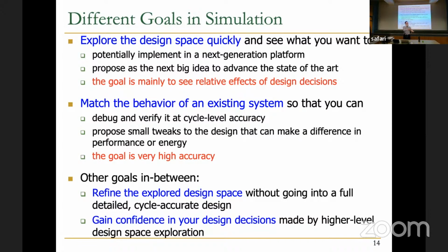Because there's a translation process over there also. People do layouts, and custom tools may not exactly translate what you envision. There are some critical paths that people break later because they find out that, okay, there's a problem over here. Let's break this critical path. Now your simulator may not be informed. So the people who designed the RTL do not know about that happening. As a result, your Verilog simulator, which is assumed to be very accurate, diverges from the real hardware implementation.